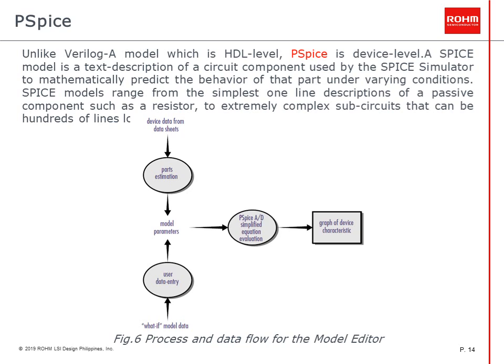PSpice AD is a simulation program that models the behavior of a circuit containing any mix of analog and digital devices. Used with OrCAD Capture for design entry, you can think of PSpice AD as a software-based breadboard of your circuit that you can use to test and refine your design before ever touching a piece of hardware. Because the analog and digital simulation algorithms are built into the same program, PSpice AD simulates mixed-signal circuits with no performance degradation because of tightly coupled feedback loops between the analog and digital sections.